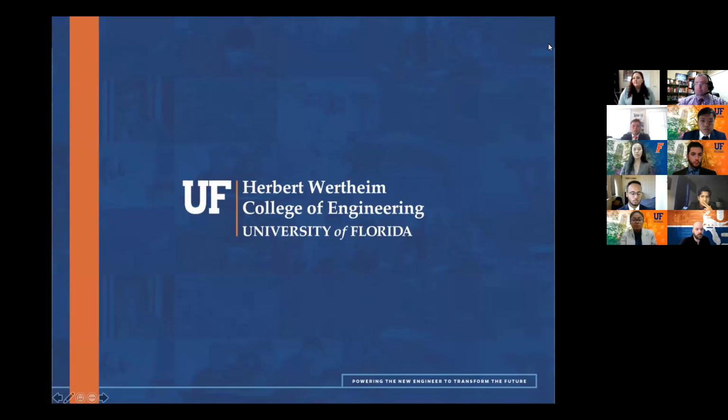I have one. Go ahead. Your XYZ motion system, it looked like for X and Y you guys are using rack and pinion. How much backlash are you going to have in your gearing, and is it going to cause problems with getting to the tiny 1 point something millimeter diameter wells on a 384 well plate?